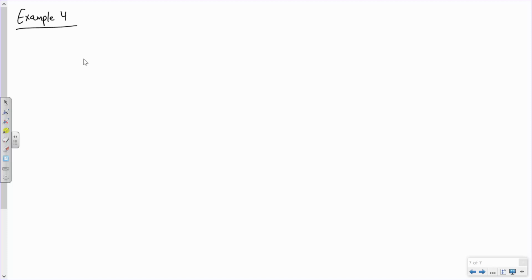Okay, so we've already plotted the curve, so let's look at our E value. So our stress equation is 17,500 epsilon, and I'll try and write the epsilon a little curly so everybody's with me on that, over 1 plus 240 epsilon. So by the way, that's epsilon, a lowercase epsilon for strain. This is a lowercase sigma for stress, so everybody's aware of that. Okay, so what I need to do is determine the derivative of that.